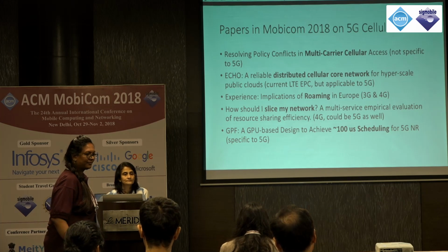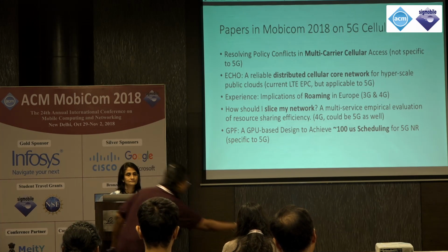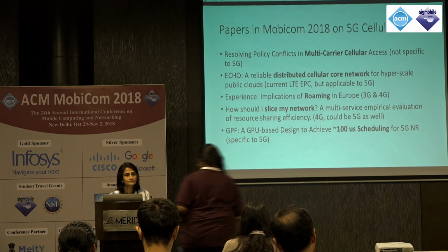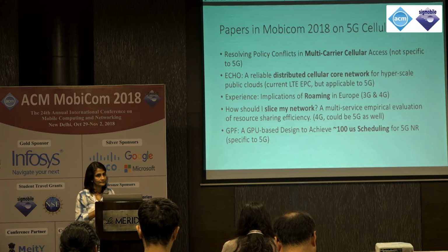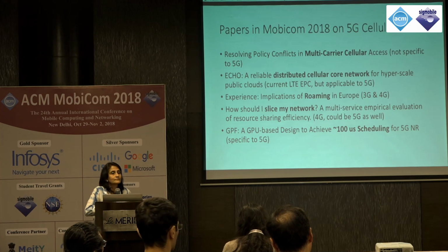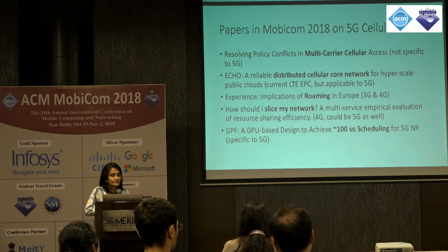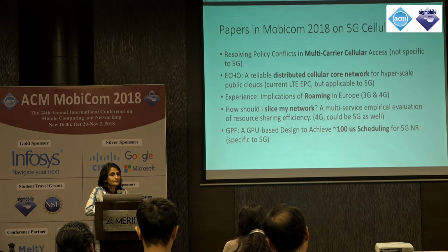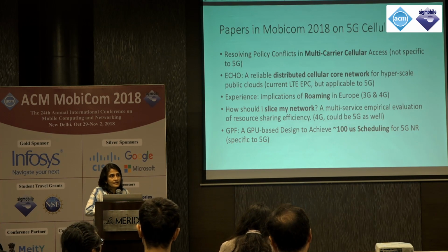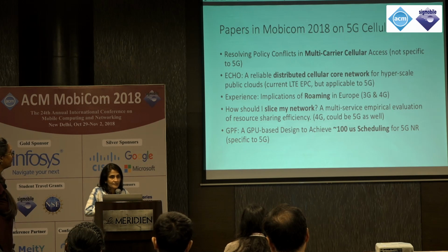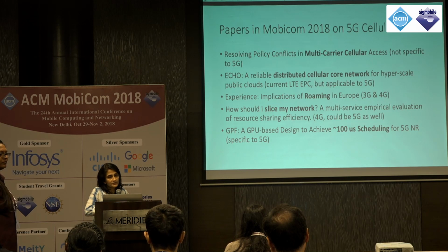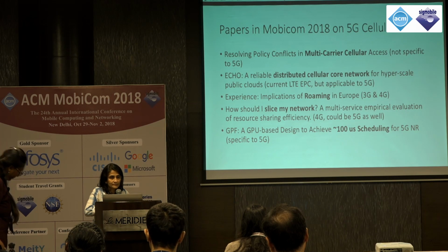What is the state of V2X communication in 5G? Is there any new modulation scheme we are thinking of, or are we relying on the current modulation scheme, or is there anything in particular we are looking at in that direction? So again, the entire 5G NR on the radio is based on OFDM. And it is a flexible framing structure, so even for V2X, it's still going to be OFDM.